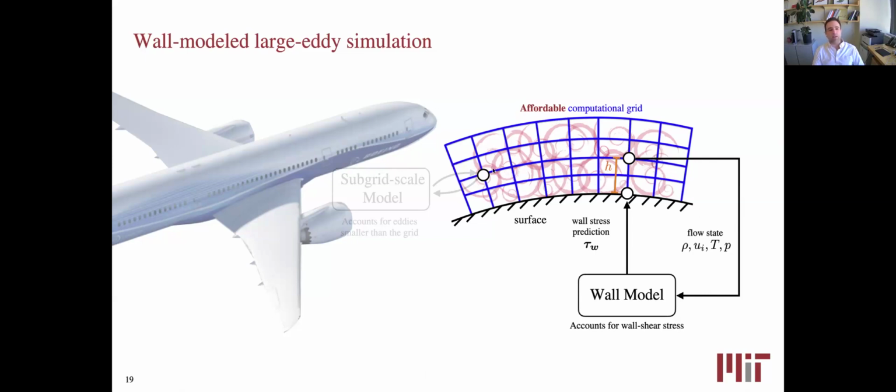And the framework that I use is large eddy simulation. And it's called large eddy simulation because only the large eddies are resolved and the small ones are modeled. And it's called wall model because also close to the wall, we account for the fact that those small eddies are not resolved by the grid. So that's why it's also called wall-modeled large eddy simulation. Okay, but there are other frameworks that are also perfectly fine. It just happens that the one I use is large eddy simulation, LES, for sure.